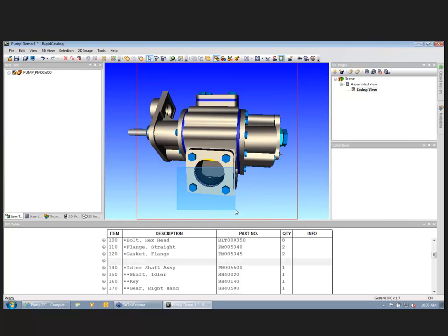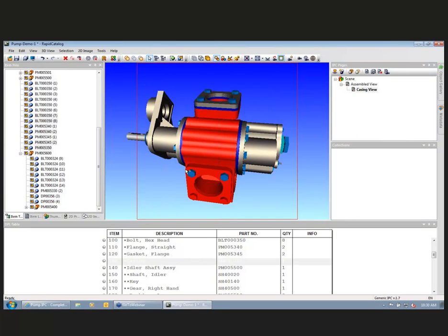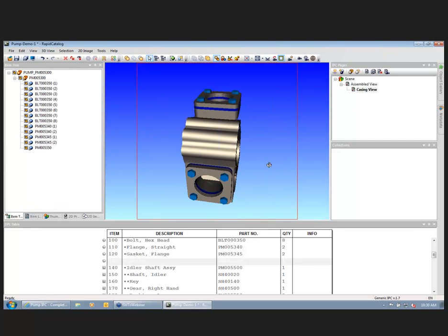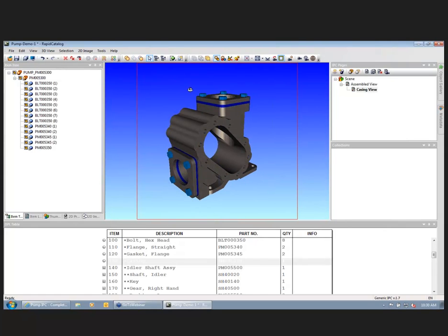I can simply do a window select. Hold down my control button to select all of the components I want to keep on this sheet. Invert that selection and get rid of the components I don't want to have on that sheet. Now notice I hit a red X there. That didn't delete the components from the whole entire project. It just removed the components I don't want to be displayed from the sheet. I can come up here and do Show Deleted Items, and any component that has been hidden or deleted from this sheet is going to have a big red X through it.